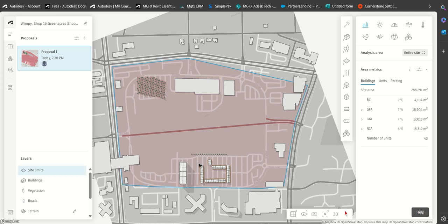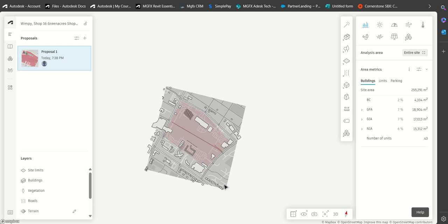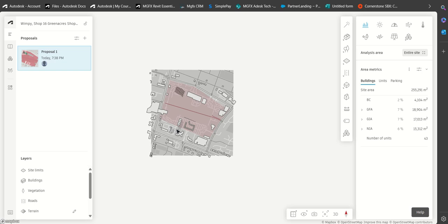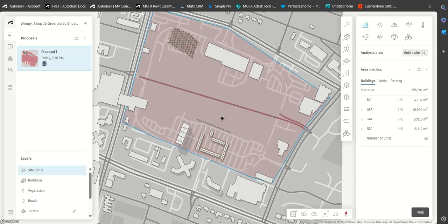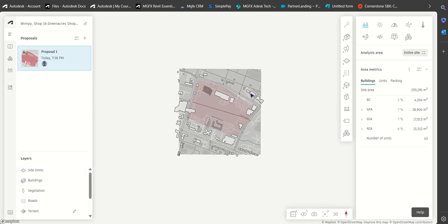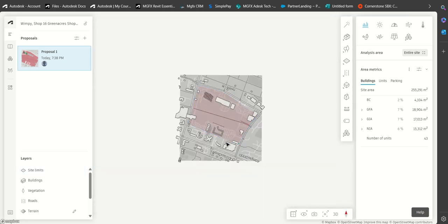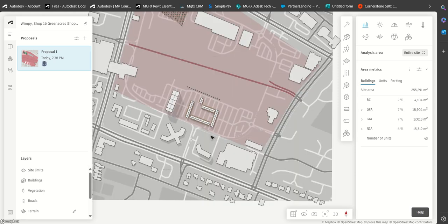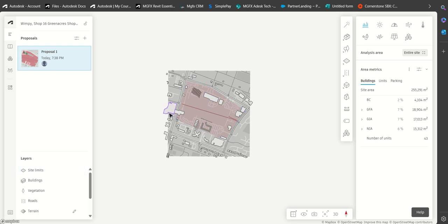And the powerful part of this entire process is the analysis that we had a look at earlier on. And then, of course, a huge bonus is that you can have this existing content. Now, when you export this to Revit, all this information will come along, including the existing information of the built environment around your site, which also helps tremendously. It saves you a lot of time having to mass these buildings from photos or from Google Maps by tracing. The information is already here, with a click of a button.